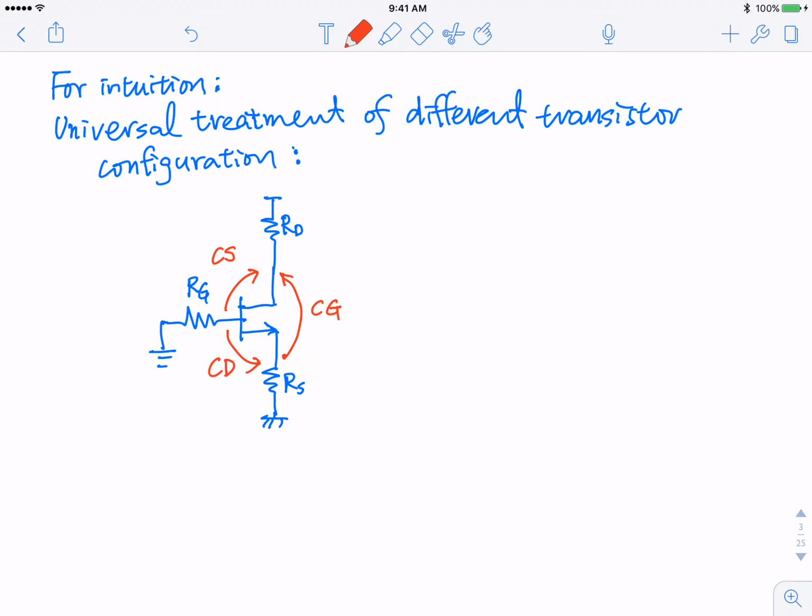So you see, in principle, for three-terminal devices, if you do random permutation, there are 6 possible permutations. But there are really only 3 useful ones. So these are the 3 useful ones. It's not an arbitrary pair. Gate driving, with output at the source, is useful. Gate driving, with output at the drain, is useful. Or source driving, taking output from the drain, is useful. Okay, question? No?